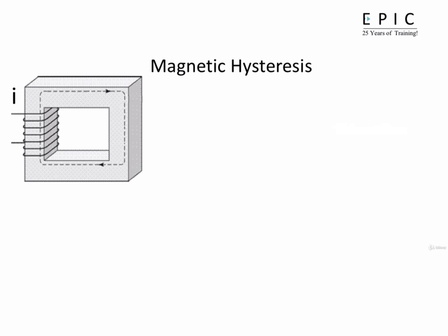Another quirk to confound our analysis of magnetic flux versus force is the phenomenon of magnetic hysteresis. As a general term, hysteresis means a lag between the input and the output in a system upon a change of direction. Much the same as what you might have experienced in an old car whose steering is very, very sloppy, and as you steer, you have to oversteer in order to bring it back in the other direction once going in one direction.